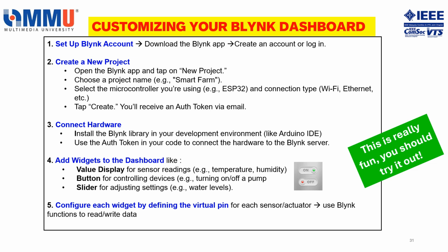Now you need to connect the hardware. After connecting the hardware, install the Blynk library in your development environment like Arduino IDE. Use the authentication token in your code to connect the hardware to the Blynk server. Add widgets to the dashboard like value display, button or slider to display the various values which are captured by your sensors.